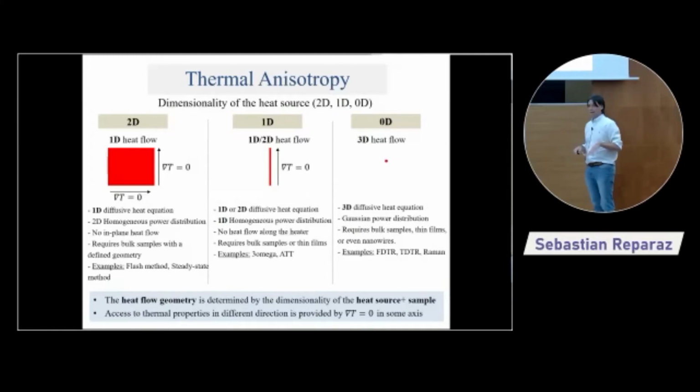If your material were anisotropic, then maybe you could, but this will be based on intensive modeling. And this, of course, is something experimental work wants to avoid, but only if you have no choice. If you work with a one-dimensional heat source, the situation is completely different. And the beauty of this idea is that the temperature gradient along the wire is 0. So you have no heat propagation in this direction.